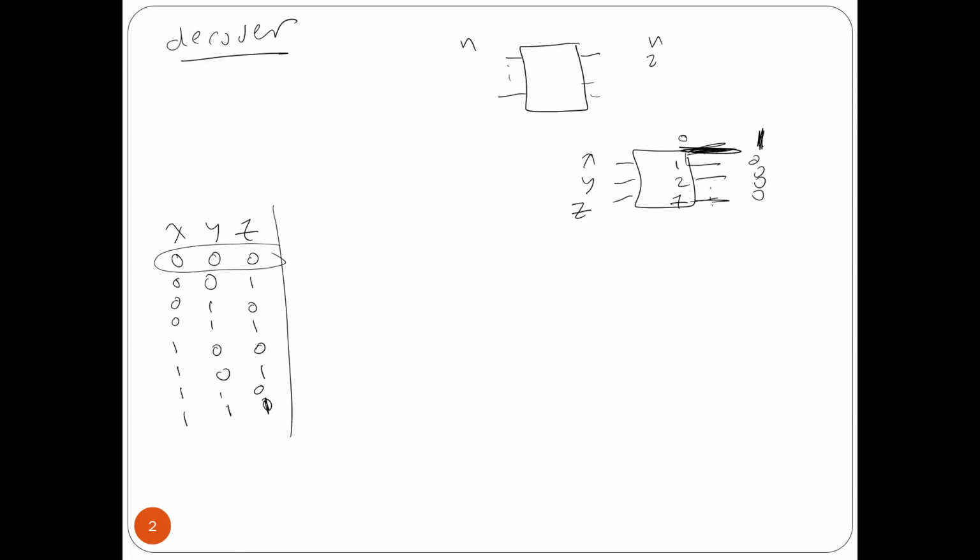Same thing. So always only one output is 1, and all the other lines are 0. Always. Okay. For example, if line number 5 is 1 and the other outputs are zeros, that means the binary input here is number 5, and so on. So in this case, the output, I'm going to call it D0, has to be 1. All the other outputs should be 0. Same thing when the input here is 7. So D7 has to be 1, and everything else is zeros, and so on.